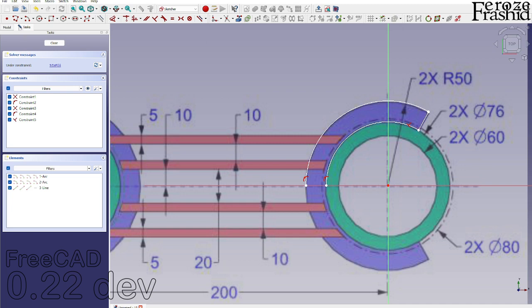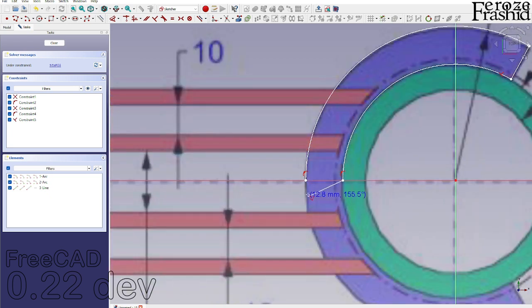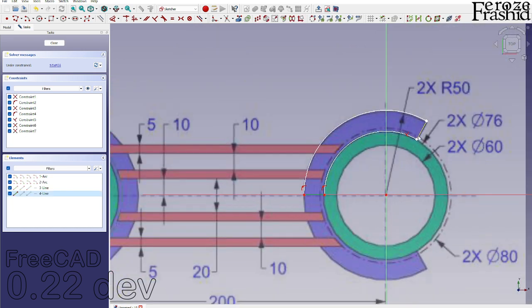One of them is that if you're drawing a polyline right next to an arc, it will take the tangential direction by default. So hit M a couple of times after you start that, and that will give you a free moving line, and that helps.